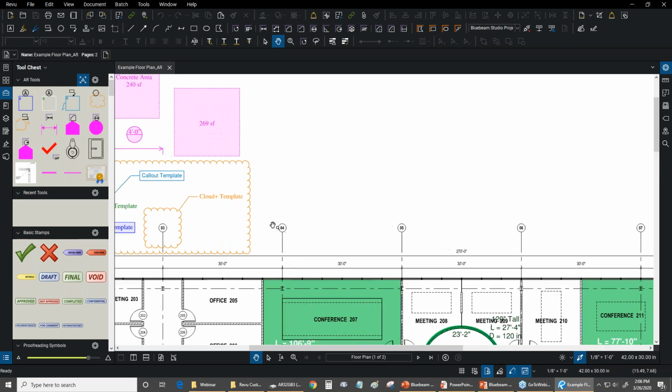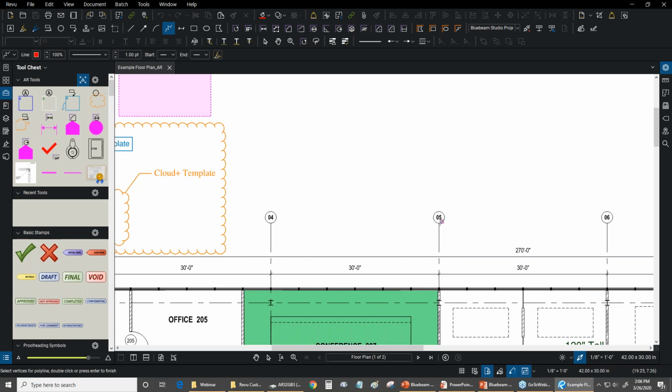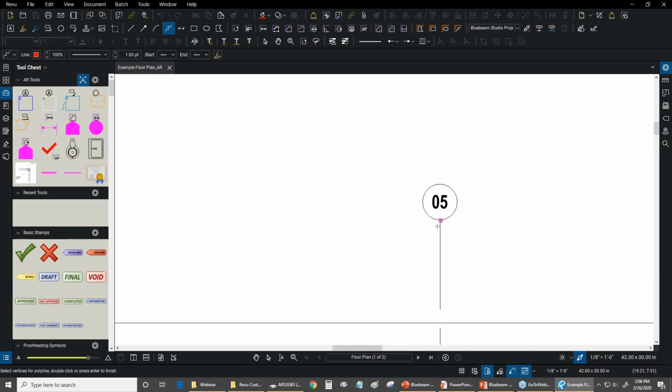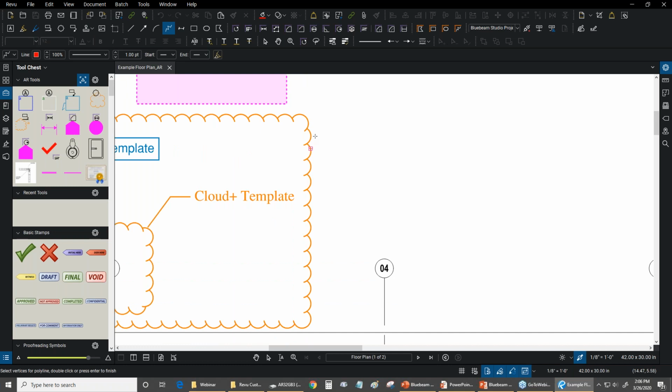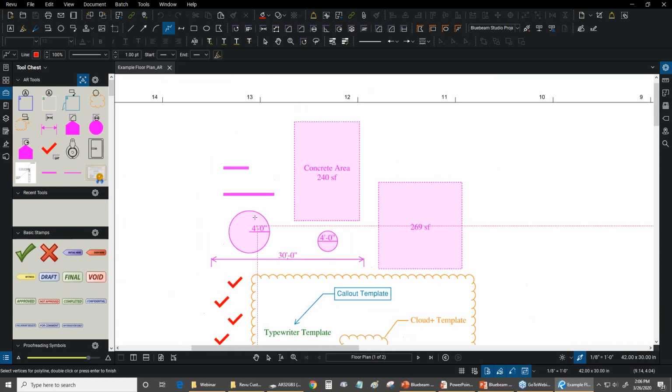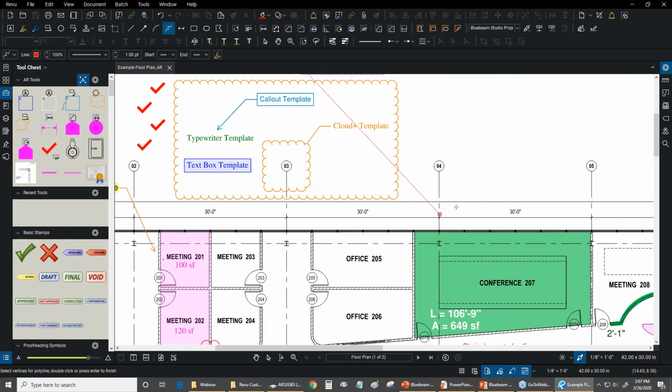Snapping to content means I'll snap to any of these vector lines that were made in a CAD or BIM program, and they have some special properties. So if I go back to my tools, markup, and let's go back to polyline, I can start to snap to these, and I can snap to their endpoints. They'll highlight in blue. That little square will highlight blue. And you can even change the color of this cursor. I've changed mine to red so I can see it a bit clearer. It's kind of like a red purple. If I go down here, I have snap to markup, and this allows me to snap to my markups. So now I can use this tool and start to snap to certain aspects of the drawing, and that is quite nice.